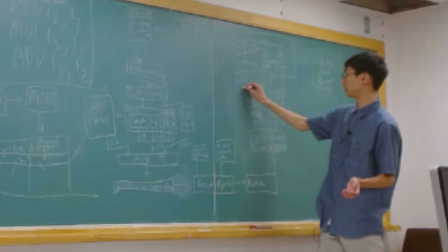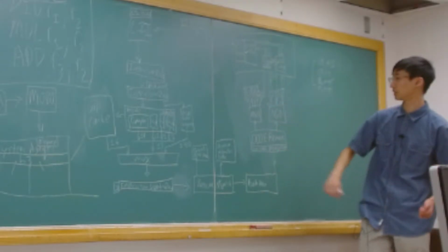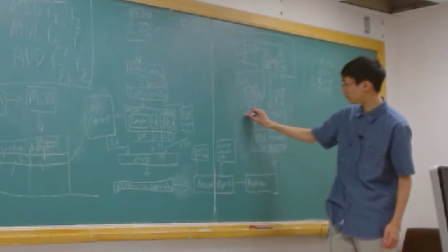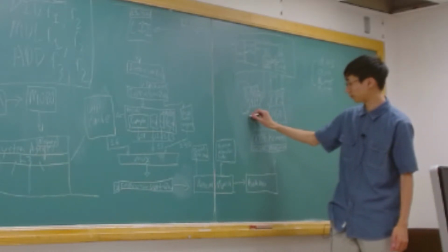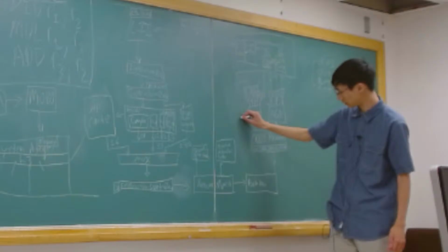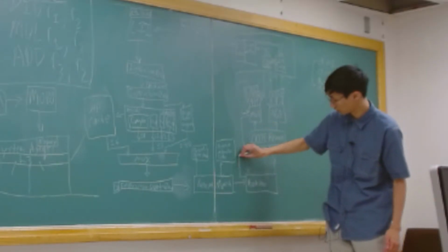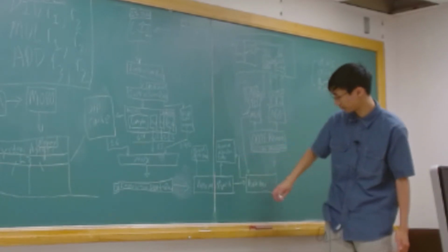Everything comes in and gets applied into these ports out of order and scalarly, and then we will pull them out. We will push them back into the math scheduler, and we will also push them out to the reorder buffer. And then the reorder buffer will push them out or interact with the register allocation table.